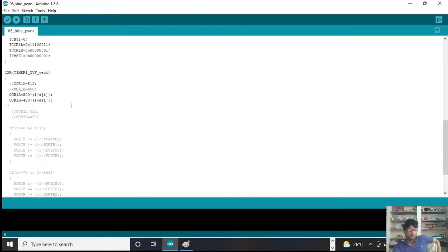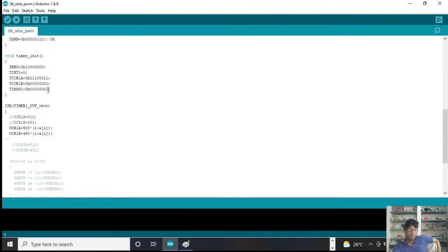And here I kept the same 10 bit settings. The timer for the PWM is 10 bit, and in the output compare register I have given 500, and here I have reduced it for 20 counts, that is the dead time. What is per count, all these things you will understand clearly when you read the data sheet in detail.